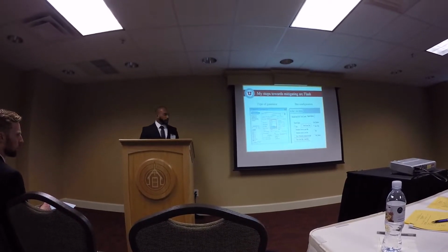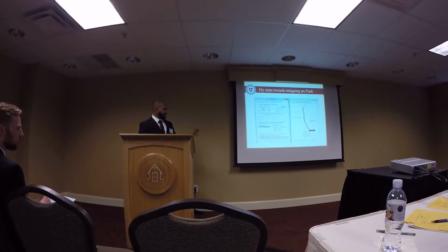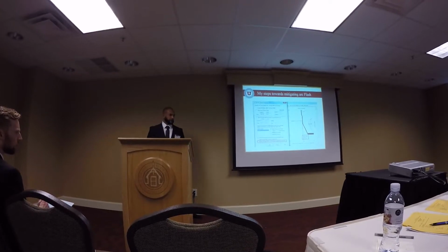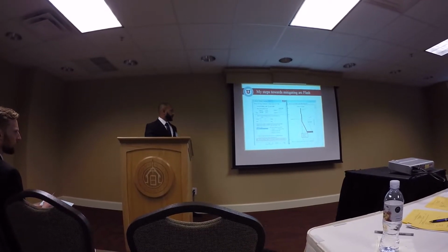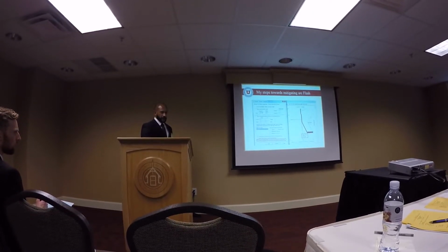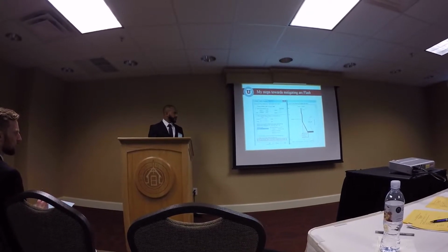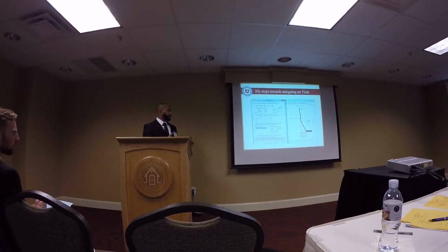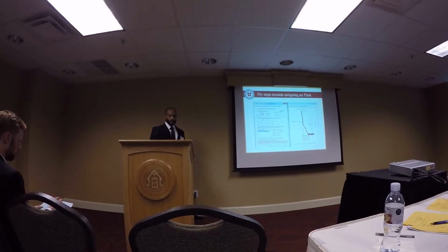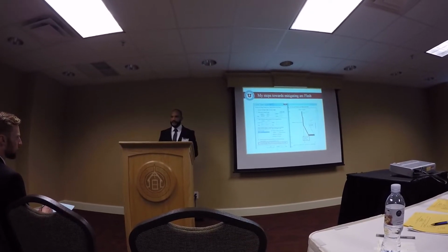rather than running it in just the general mode. Once I configured SKM and ran the study on a selected area, I get a TCC curve, which is a time current curve. My partner went into great detail explaining it, so I'm not going to repeat myself here. Once I get the TCC curve, I know what the risk level is, what the instantaneous energy is, and the time the generator main breaker takes to activate.